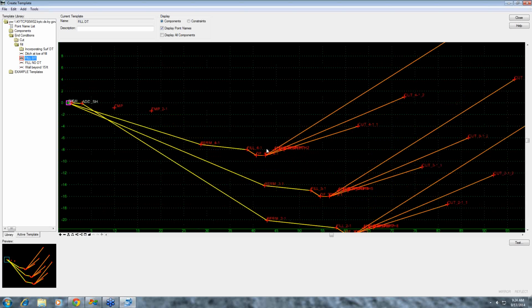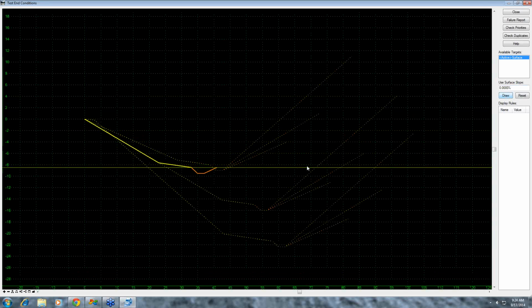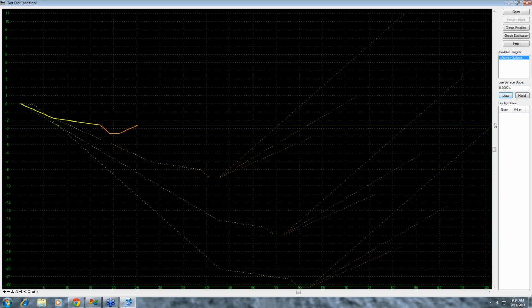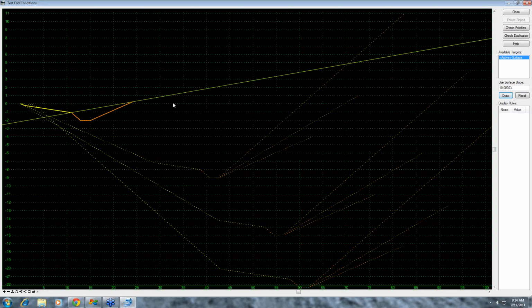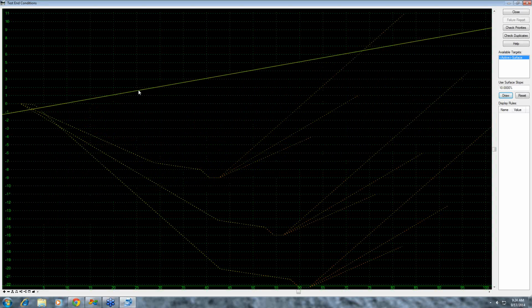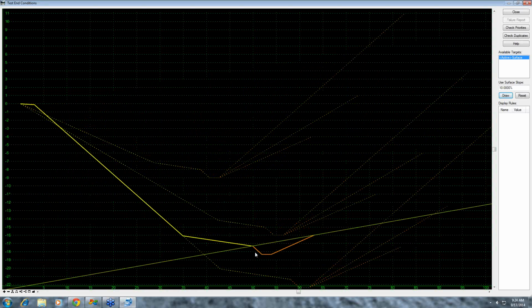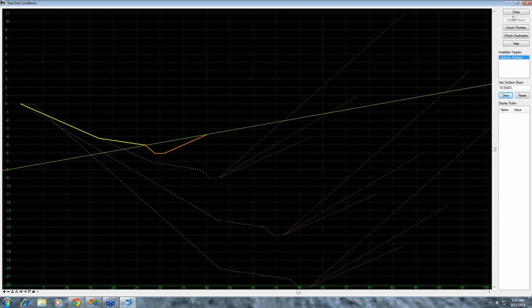It does have a minimum depth on it of 1 foot. If you've placed the surface ditch and you've run it through your template and it has not failed, it's because you didn't meet the minimum depth. It'll run through all these different alternates, but that's why it didn't work. This one works great when you're at a 0%, or if you're at a 10%, or a positive percent. Anytime it's catching that slope, it's going to work, and it's set up to do multiple slopes.